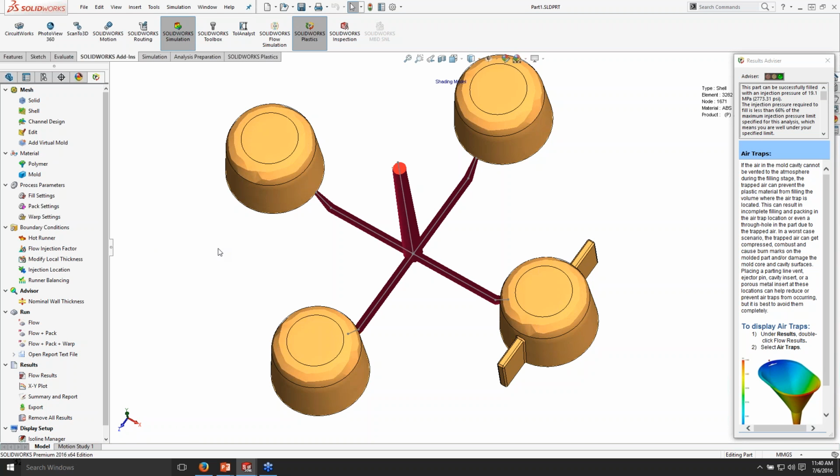And as you go through the fill balancing exercise, I will tell you this: with the simulation that I created, the first shots on my customer's mold were about 2.5 weeks ago, when they did a short shot analysis and compared that to the simulation. It was within 1% of the simulation. So I will tell you that SOLIDWORKS Plastics does a very, very accurate job in runner balancing, in that I can see it in simulation, I can turn around, get physical parts from my customer and literally look at both of them side by side. Again, 1%. All right. Thank you very much, Chris.